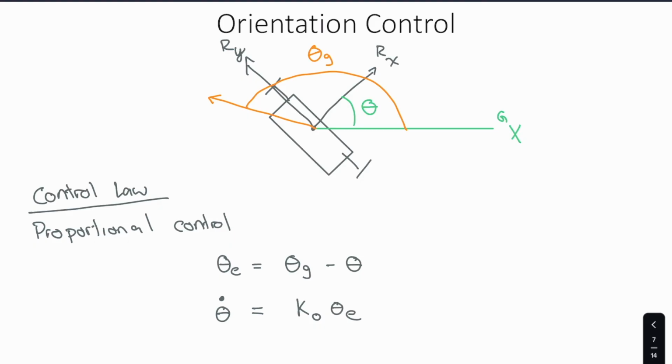And this is why we call this a proportional control law, because the value we're setting for theta dot, which is the angular rotation rate of the robot, so how fast are we rotating this wheel forward and how fast are we rotating this wheel backward, it's going to be proportional, by some constant factor that we'll have to tune, to the current angular error.